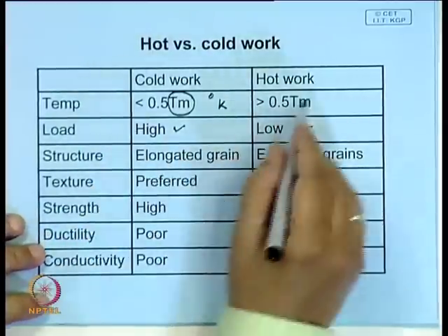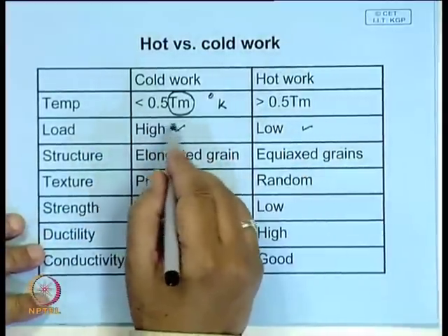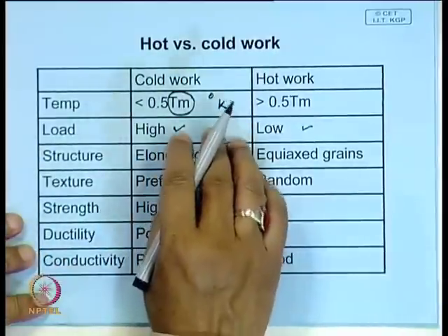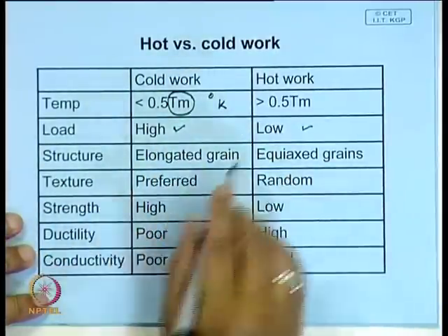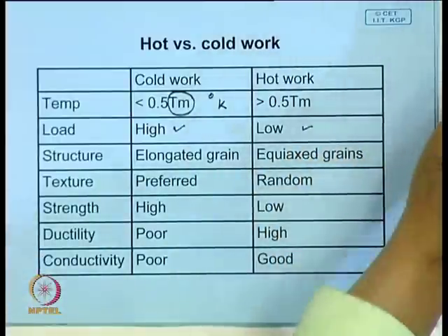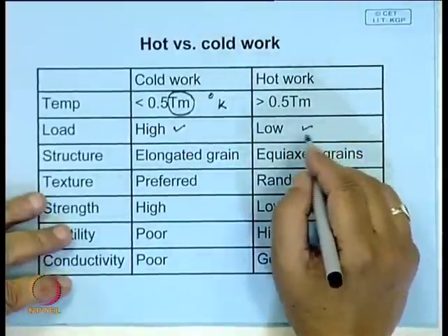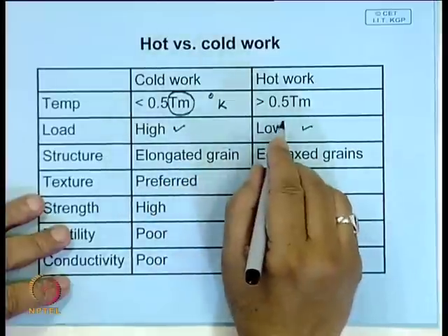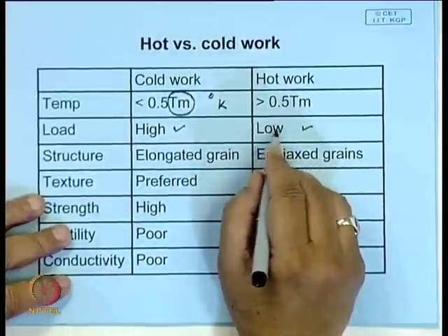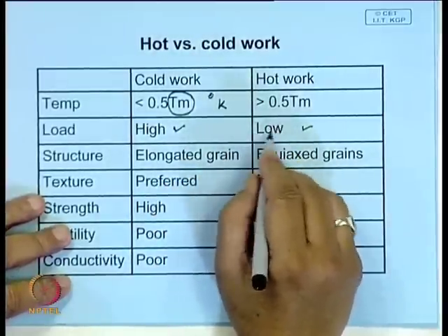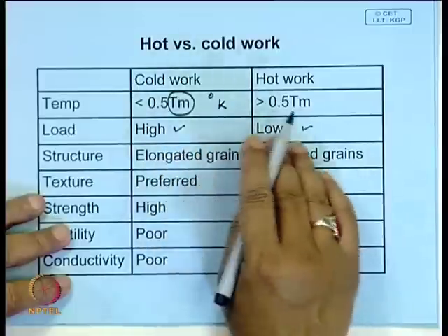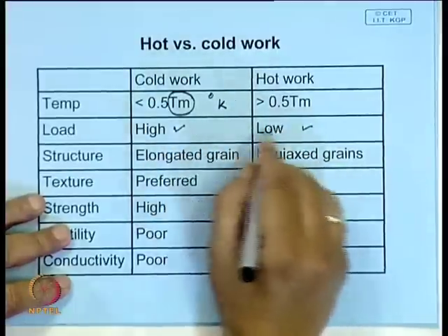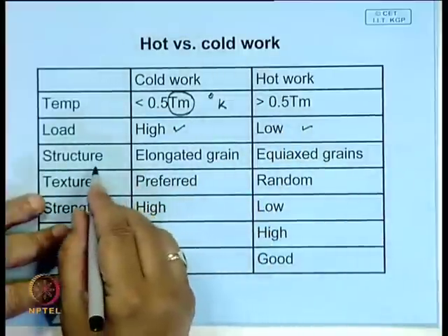But there is an advantage of cold work, because in cold work there is no interaction with the environment; it is more or less inert, whereas in hot working, depending on the material, you may often have to offer some kind of protection, or else there will be scaling loss. Some of the metal will oxidize and the loss will be relatively high in hot working.